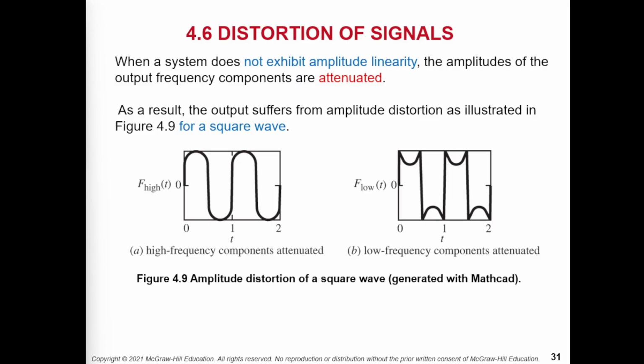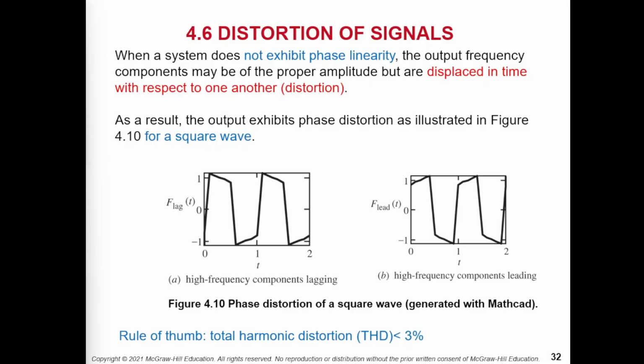So let's take a look at this time domain signal. This is the original square wave, because we take the square wave as the example. But this one is close to the square wave, but something is different, for example, at the corner. When this happens at the corner, most of the time it means the high frequency. At the center it represents the low frequency, and that means there is some amplitude distortion of the square wave. But this is not phase. I would like to talk about the phase first.